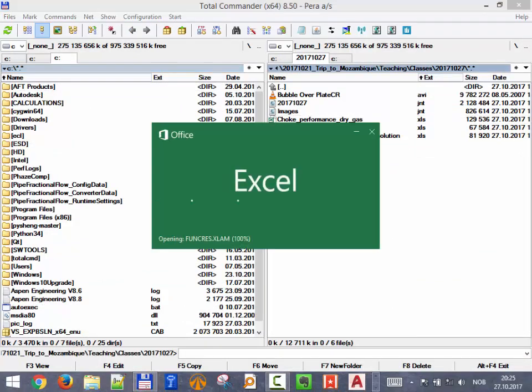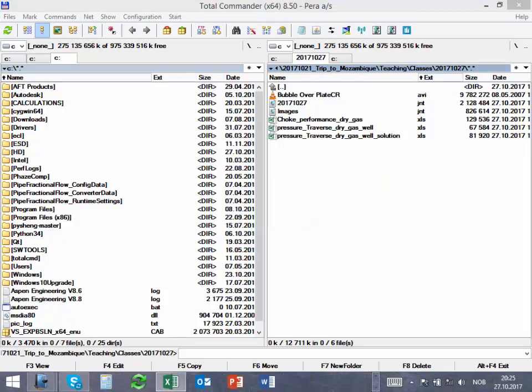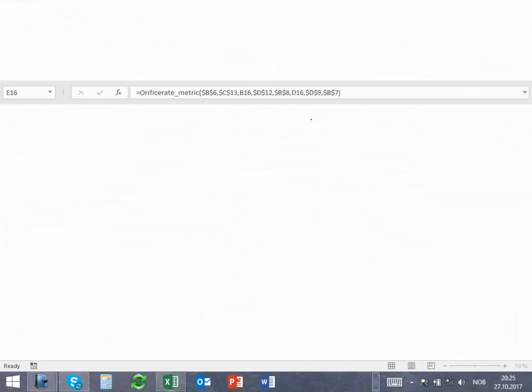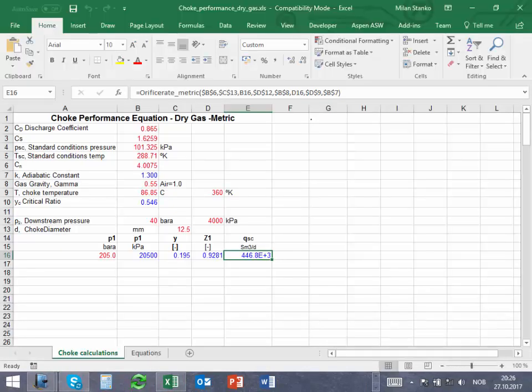And you don't have to worry about this ugly equation. I already programmed it for you. But I feel obliged to show you how it was derived, because all choke models are the same. Momentum equation between inlet and throat, and you have to assume that the gas or the fluid is passing through a thermodynamic process from 1 to 2. And then you try to simplify. But they're always based on the same. So you open that equation and you get this one.